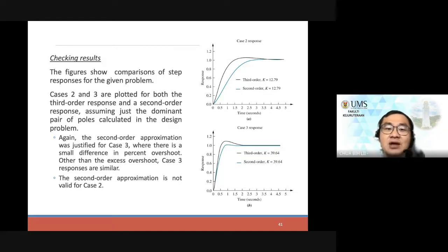And from there also we tried to use the concept of a second order system, because we only have second order system equations to estimate the peak time, the settling time, and so on. We use that to estimate, but with conditions, based on the root locus technique, right? So I hope that you have learned properly from these slides, and just make sure you check the k value, do the trial and error. A few points is sufficient, right?